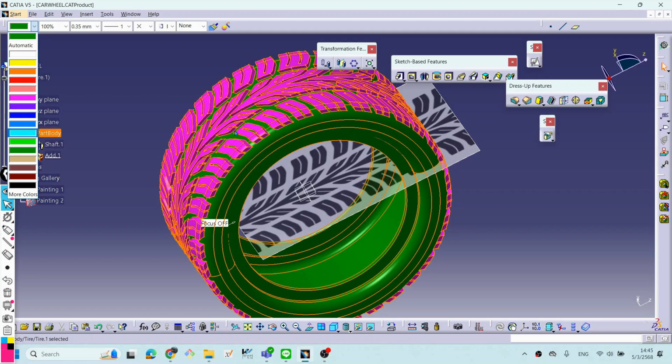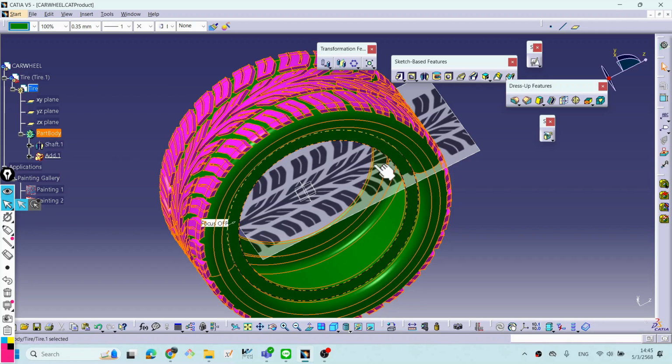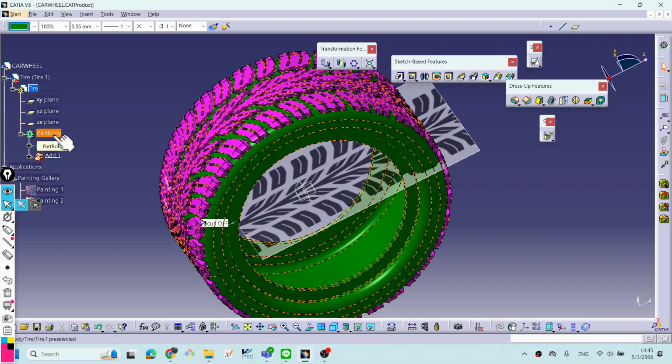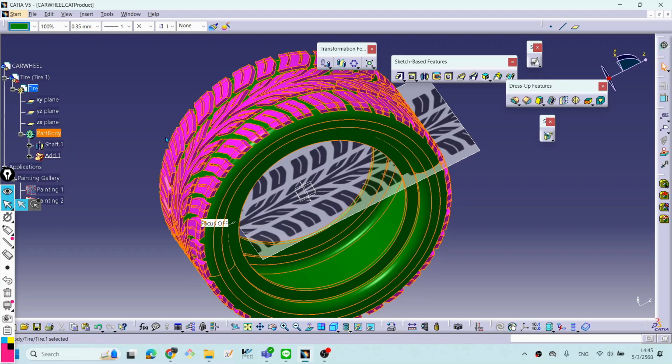The one color can be the same color across this part, because if you add up and define the color later, you will get one color. If you define different colors individually on the parts before you add them up to one, then after that the different colors will still show up on the part body after you add up, because you defined them individually before you add. That's the add function.